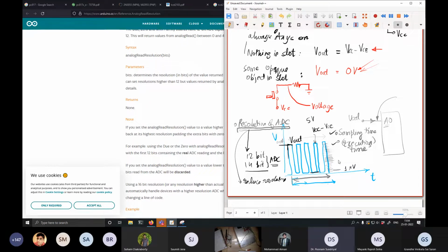If the RPM is changing very quickly, you will not be able to find out the change in RPM. You will only be able to do it after it samples, after it calculates the RPM, it displays it on the screen, then it loops back and again samples, then executes the code, then displays it on the screen, and again it loops back. So this is what's going to happen. Any other doubt before I go sit down and show you the actual circuit?